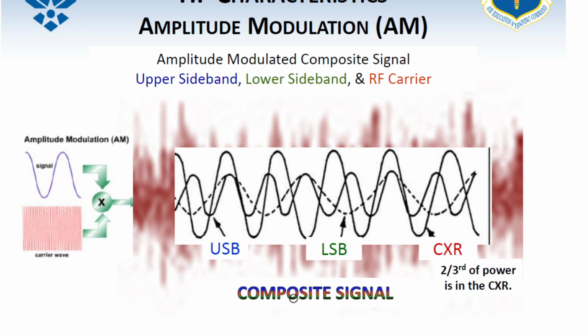So the carrier has 2/3 of the power. How much power do the sidebands have? 1/3. Okay, 1/3. Nope. So how much? They'd each have 1/6. There we go. Well done, guys. I was about to try to make you do math, but McCusker just dropped it. Do you guys understand where that number, 1/3 on each side, comes from?